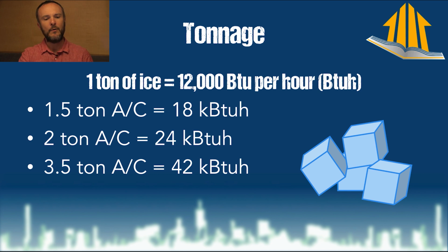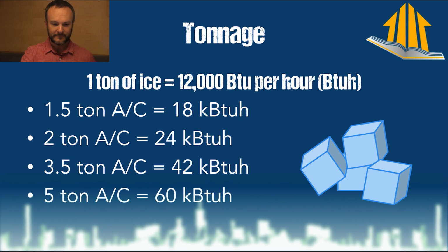You'll have a lot of people who say, well, the Manual J says it's 2 ton, but we're going to install a 2.5 or a 3, just to be sure. You want to make sure not to let that happen, because the idea behind this software is you do the calculation, it gives you the number, you install the number, that's it.